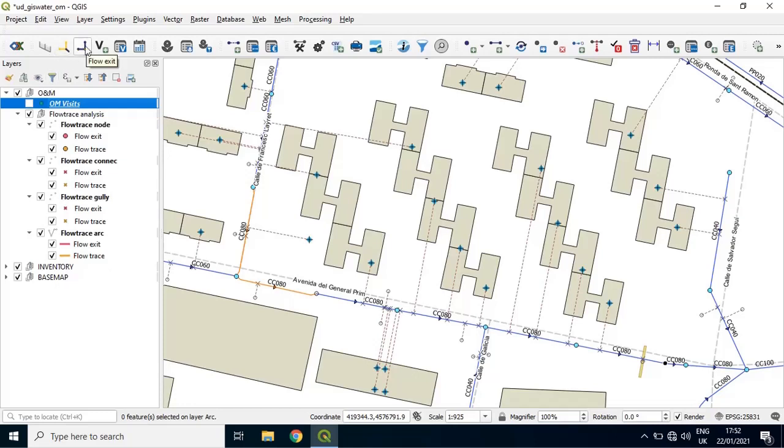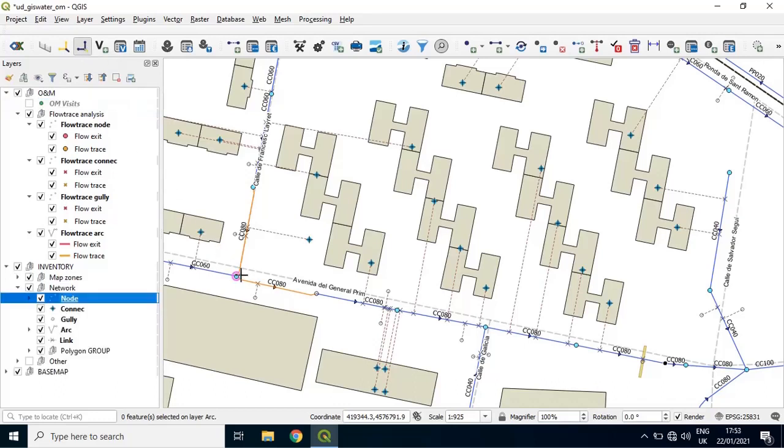Selecting elements which are located downstream from the selected manhole. To make this selection, the tool searches in the manholes contiguous with the selected one, comparing its maximum height, and in case it is higher, for upstream, or lower, for downstream, it selects it and continues the search until the end